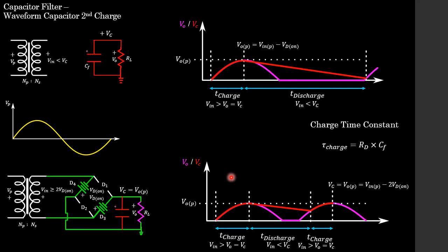What we're going to see is our diodes are now going to be forward biased. We're going to have a diode current which flows from this point through our circuit. That diode current is then going to have some current going into the capacitor and some going into the load, and that's going to now charge our capacitor for this next rising edge, which is caused by the negative half cycle. And of course, now we can see that our capacitor voltage is exactly superimposed on the output voltage.